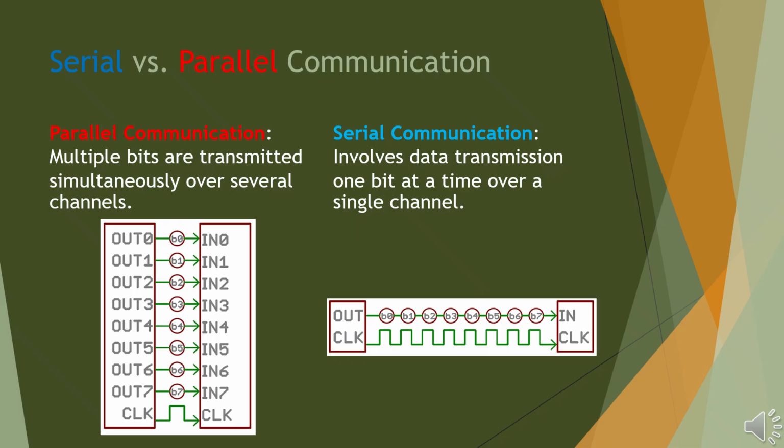In theory, both data rate and throughput can be increased either by adding more wires in a parallel bus or by increasing the clock speed in a serial link. However, raising the clock speed is generally easier and more scalable than adding physical connections. As a result, serial communication has become the dominant choice in modern digital systems.